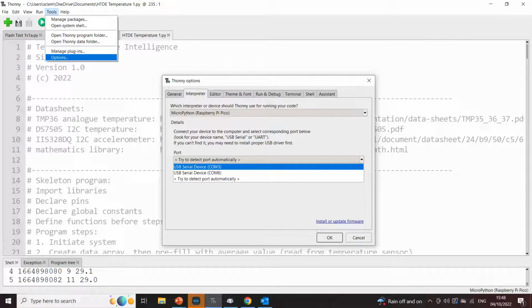I think if you're actually seriously into doing floating point stuff, the Pico is not the greatest processor on the grounds that it has no floating point hardware. Your better bet would be to go for something like the SAMD series. I think SAMD 21 is quite commonly available, which have instead of a Cortex M0, they have a Cortex M4. Okay, well that's better, isn't it? That's got a proper floating point arithmetic. And that's got the proper floating point hardware.